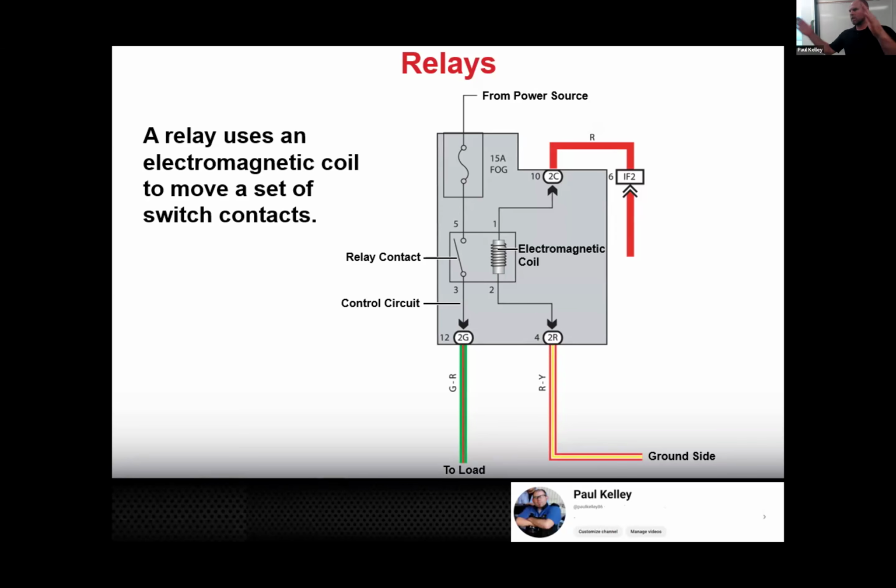And because that relay is opening and closing, there's always the chance that the relay actually welds itself closed. So if the relay arcs and arcs and arcs and does a little weld, now 5 is permanently connected to 3, what's the customer's concern? Yeah, the fog lights won't shut off and it kills the battery. And you hook the battery up and you're like, the fog lights are on. And you're like, oh, something's shorted. Well, yeah, that could be true, but the relay actually could be welded closed.